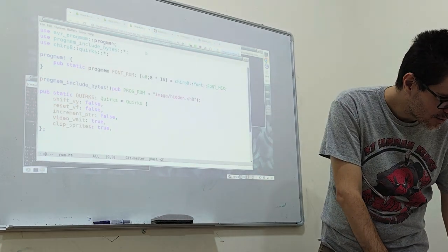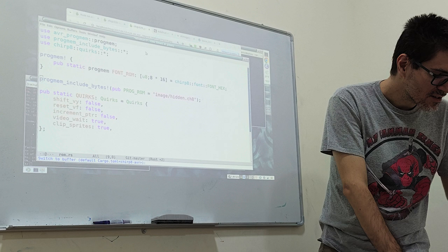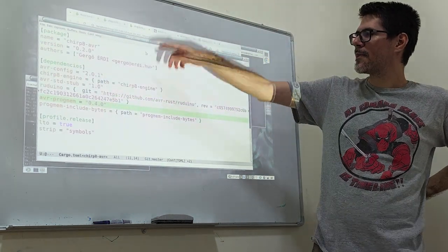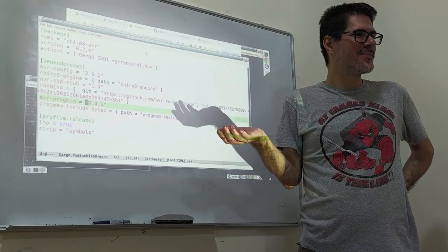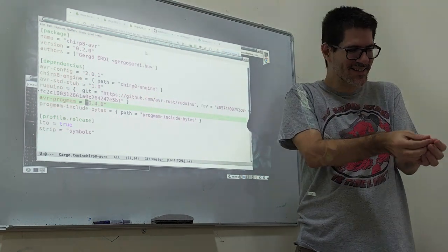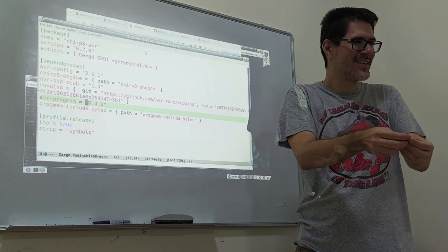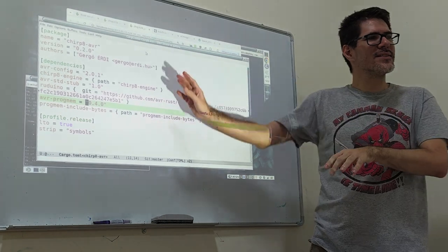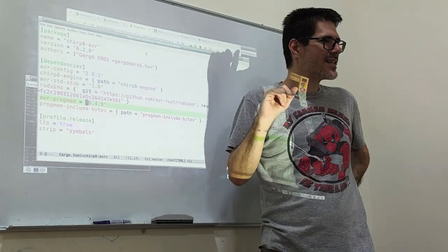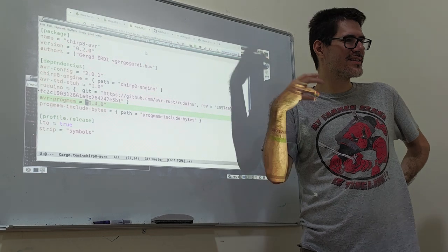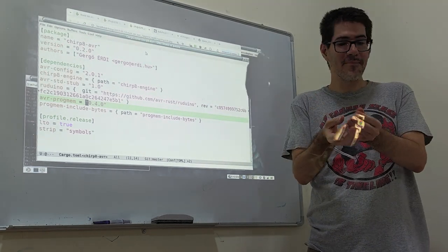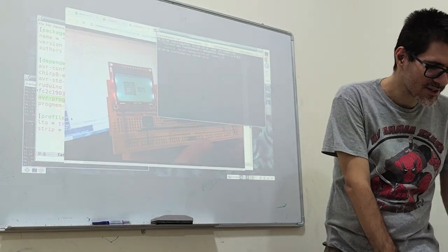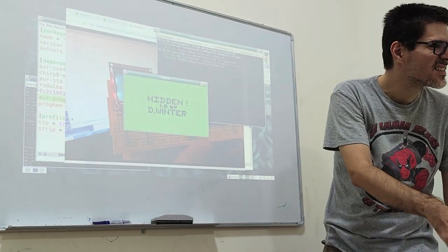So you have this package which links to the engine. This is much harder to debug because you're going to run it on a small box, a small piece of plastic. So my advice would be, if you do anything like this, always structure it like this, so that you can debug your engine or your backend or whatever your functionality is separate from the AVR or the embedded context. I was doing all the debugging of making sure that my chip-based implementation is correct using this thing.